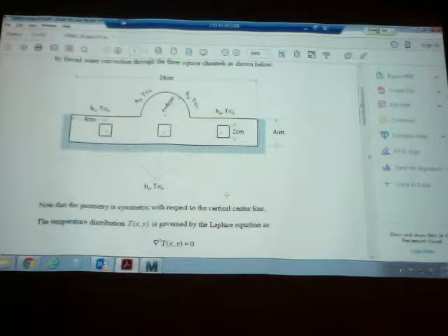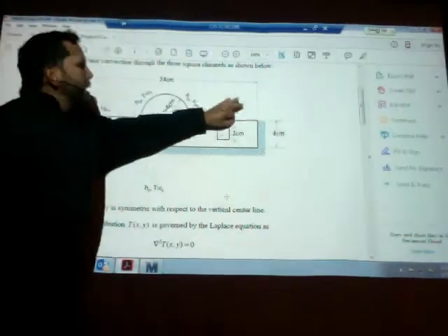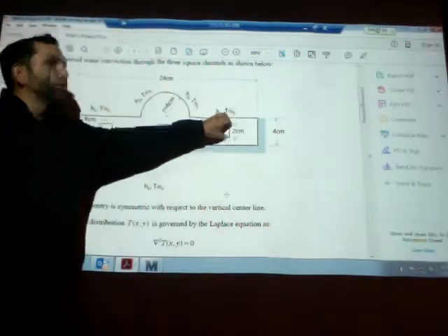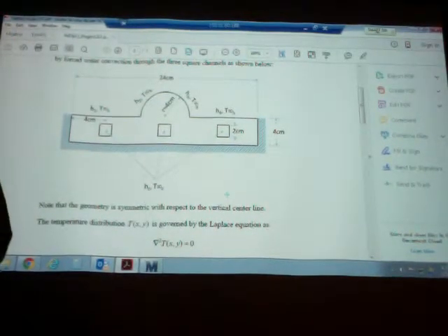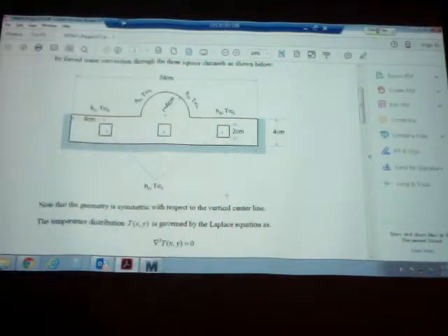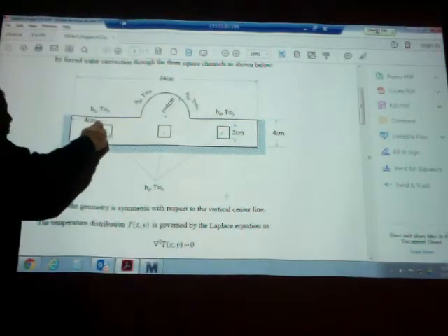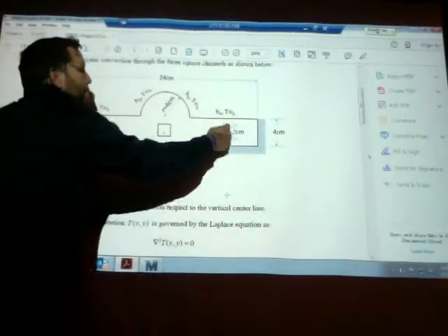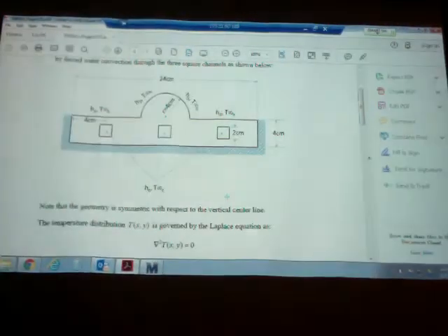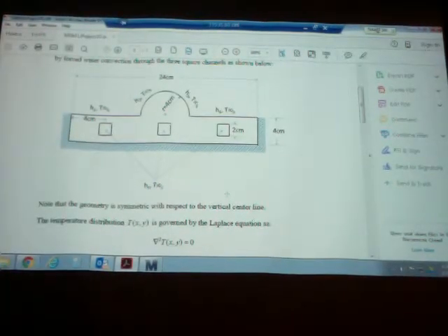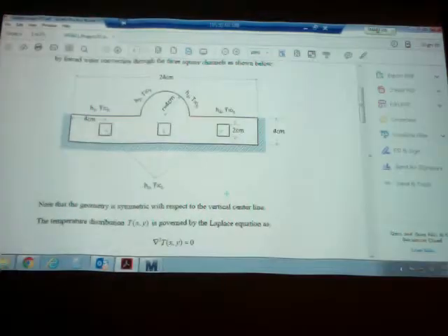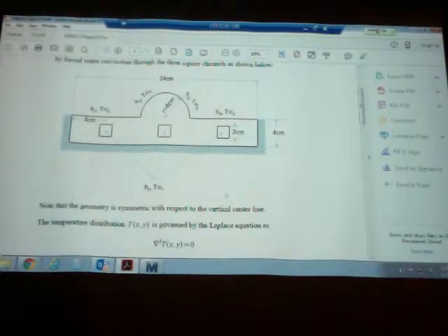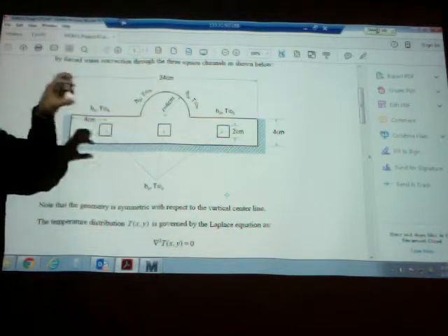So the amount of energy that is added through here has to be identical to the amount of energy that is removed from here. Okay? So all you have to do is take the output file, look at the Q's, multiply each Q by its own length, add them up, and do the same for the other surface. You do that in Excel or by hand if you want to. But remember, you're going to have like 30 or 40 of them depending on what discretization you use. And then calculate the amount of heating and the amount of cooling.